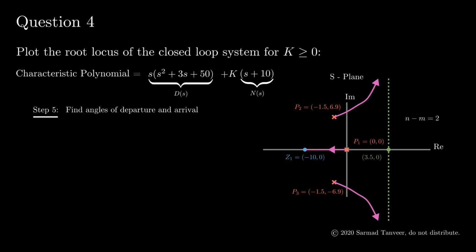On a root locus plot, when k is equal to 0, the plot starts at the poles. The resulting root locus plot shows how the location of the poles change as k approaches infinity. This means that in each root locus plot, there are only as many branches as there are poles. The branch of each root locus departs at a pole and either arrives at a pairing 0 or simply approaches an asymptote as k increases to infinity.